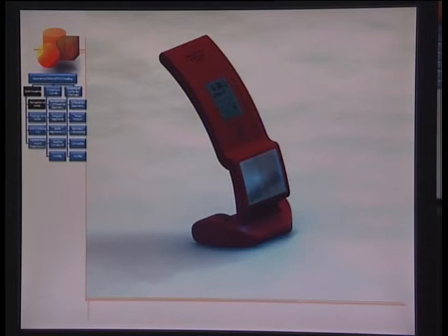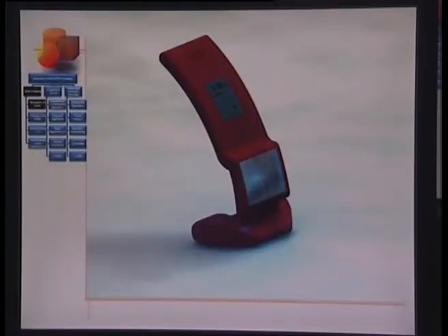Sir, for the compact purpose of the lamp, we have used LED bulbs, so that the size of the lamp can be compact. And because of the rechargeable battery at the bottom, the center of gravity is going to shift downward. That's why it is not going to topple. Oh, the battery is heavy. Okay. All right. So this is what we have from group 2.